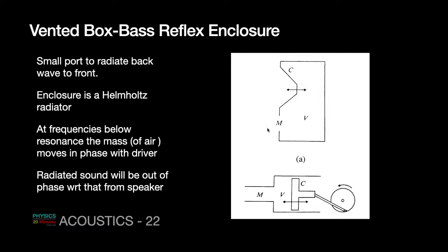This is very typical of a Helmholtz resonator. Some few of you are doing some experimental work on that as well. Helmholtz resonator, so you are familiar with that idea. You drive it at one end and let the energy escape on the other end. So the important point that we have to remember, this is the mechanical analog. Like this is the speaker. So the speaker is represented by a piston which is vibrating back and forth, and the mass of the air